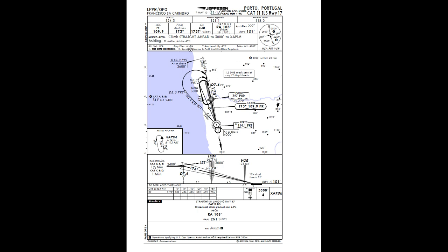In case we join the ILS, we will just turn the altitude window to 3000 feet and continue the go around, in case we are going to go around. ILS is 109.90 is the frequency, and the localizer direction is 173 degrees. Runway 17.